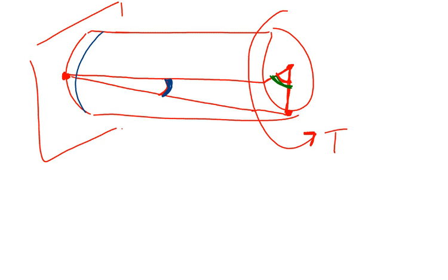If we look at just one of the squares, here is the square before it deformed, before we apply the torque. What happens to that square after we apply the torque? Remember, this was its bottom edge. This is now its bottom edge. That square deforms into that shape. Hopefully everybody can see that.